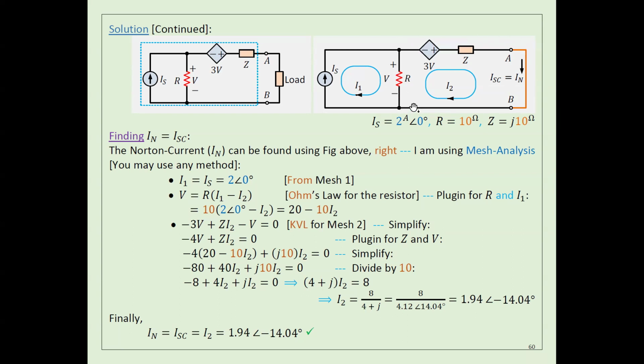For this current here, this one is V, so this one should be 4V. And the current through Z is actually 4V minus 0 divided by Z. So now I have an equation that has only one unknown, which is V. Let me say it again, look here, guys.